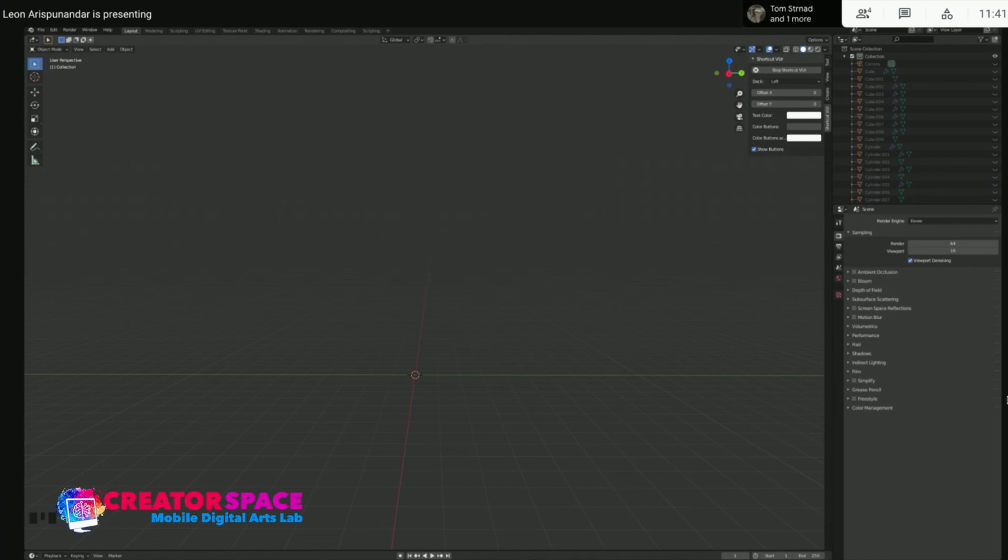I have all these add-ons here. You click on the add-on zip, and then you just click install add-on, and that's it. You turn it on, and you've got the M3 add-on installed in your Blender. That will be the same with every single add-on that you want to install in Blender.